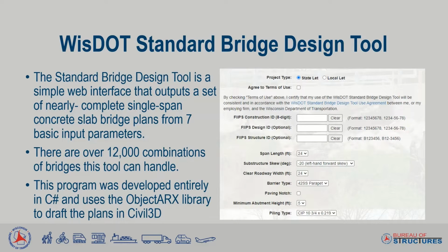The WSDOT Standard Bridge Design tool is a simple web interface that outputs a set of nearly complete single-span concrete slab bridge plans from 7 basic input parameters. There are over 12,000 combinations of bridges that this tool can handle. This program was developed entirely in C# and uses the ObjectARX library to draft the plans in Civil 3D.